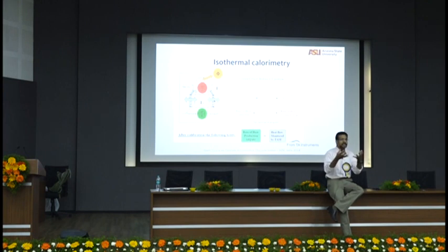When you have heat being released in the structure, two things happen, like in any heat transfer process. First, your cement hydrates and you cause heat. That heat, like I said, everything wants to be in a state of equilibrium, so it would try to equilibrate the system with whatever is the ambient.